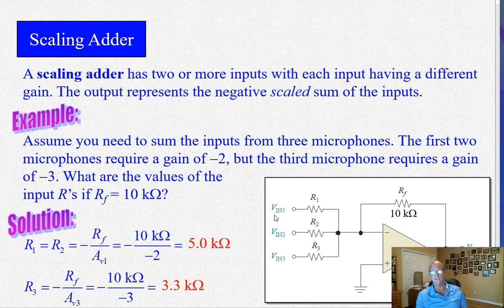And what that does is it gives your microphone for the lead singer here, the microphone for the backup singer here, the guitar amp here, and keep going with resistors. The bass amp, the kick drum, the bass drum, the organ, the trumpet, you name it. You have all the different channels of audio here, and the audio mixer is changing these resistors with their potentiometers, or sliding them up and down to give these different relationships for different scaling or different weighting for each one of these inputs, so that they're either louder or not as loud depending on how the mixing engineer is setting up the track. Okay.